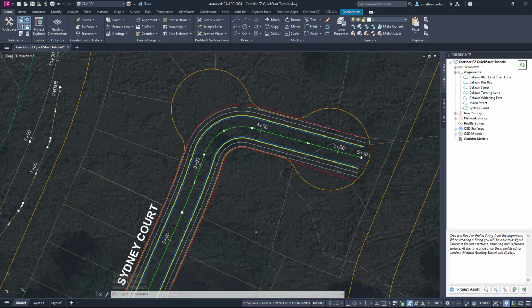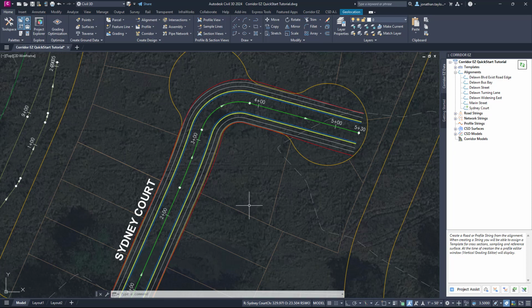If we draw polylines or blocks or anything like that, or even attempt to create the corridor right now, the speed at which you can operate is very slow. So the intention with this is that you build your model and your road designs up incredibly quickly, and then you can begin to look at output of, say, polylines if you want to, or even the corridor.